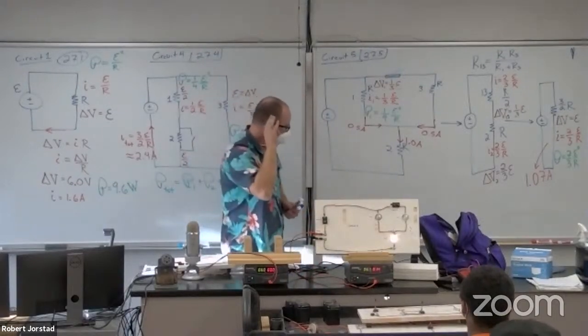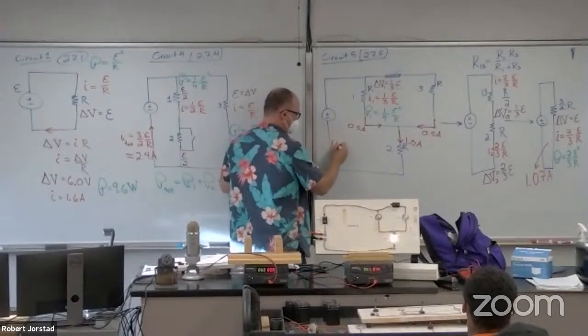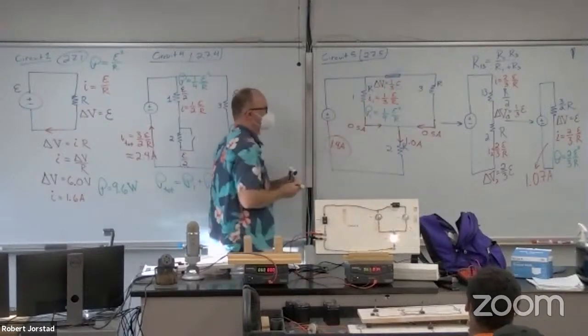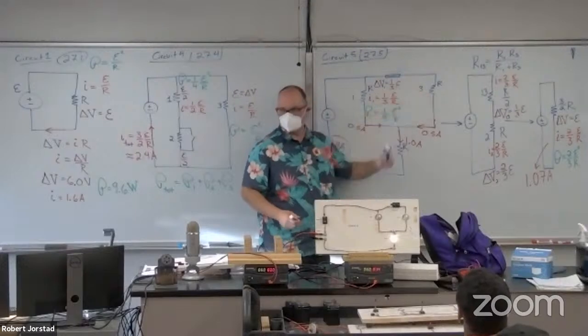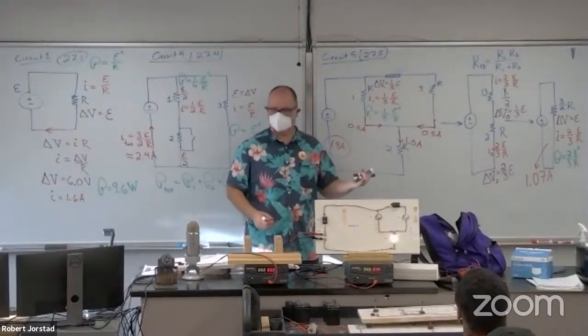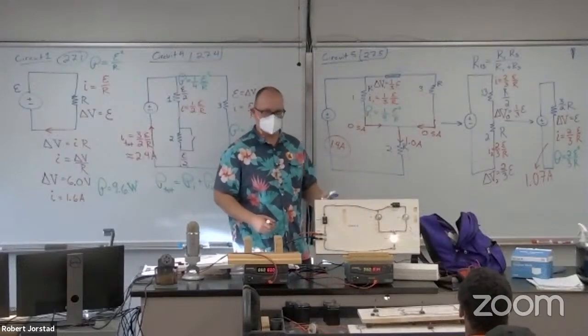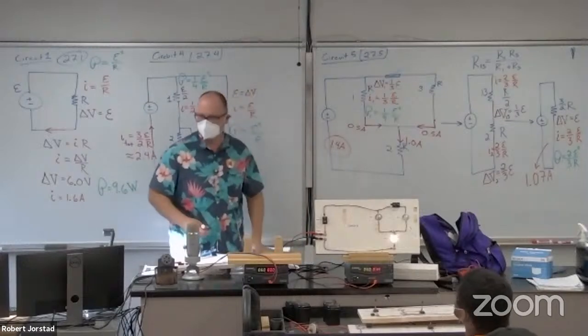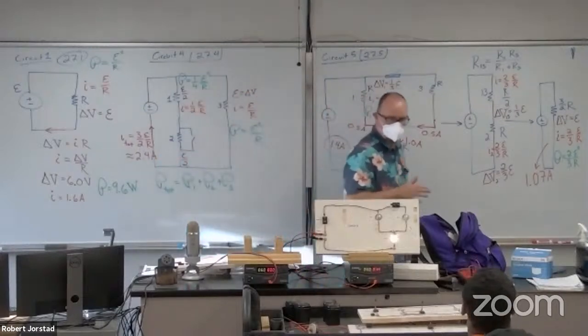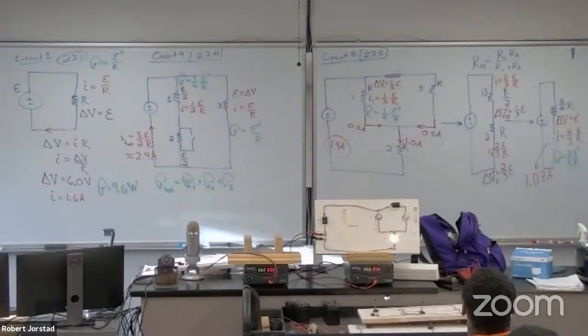What is it? 1.4. So clearly the issue here is these two bulbs are not getting warm. That means their resistance is awfully low, and that means we're getting an artificially high value of the current here. Are you starting to feel the intuition a little bit?